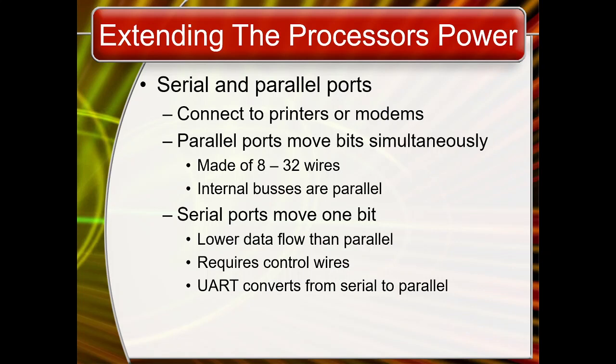Serial and parallel ports were used to connect printers or modems. Parallel ports move bits simultaneously. They were made up of 8 to 32 wires, and the internal buses used are also parallel. As compared to parallel ports, serial ports move one bit at a time, with lower data flow than parallel, and they require control wires. A UART converts from serial to parallel. So this is the device for converting serial to parallel.